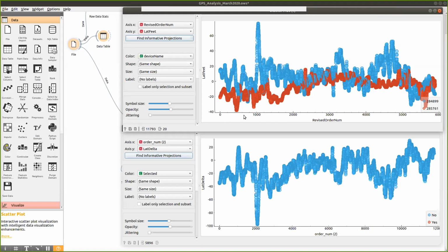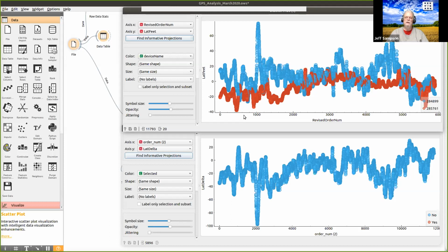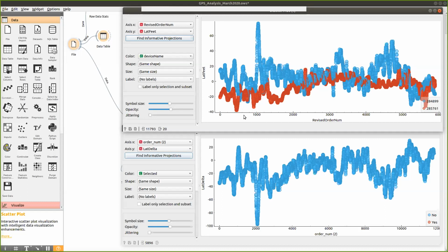So you think I really need to get the Wisconsin Department of Transportation correction data, just like I think you're using Minnesota's DOT? Yes, but your receiver has to be smart enough to understand that, and I'm assuming the one you have does not understand that data. Yeah, probably not. And if it does, I wouldn't understand it yet. You might be able to get raw data out of it. If so, at least you might find it interesting to do some post-processing, if not in real time.